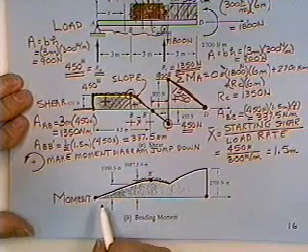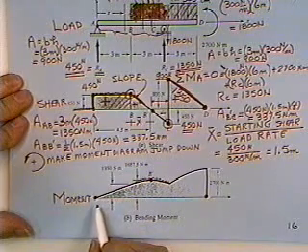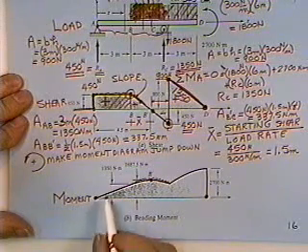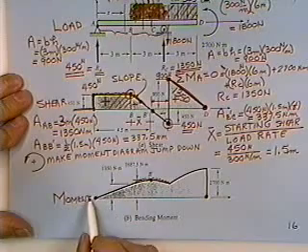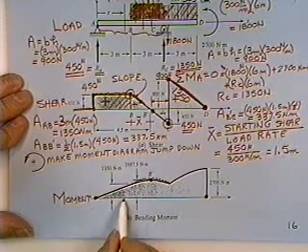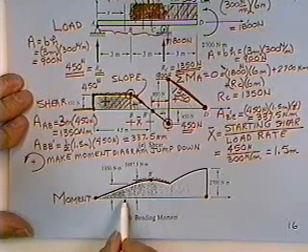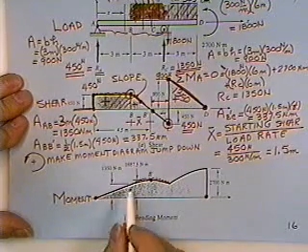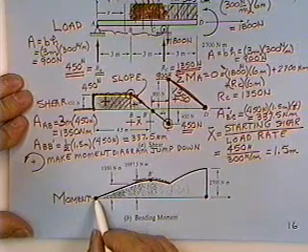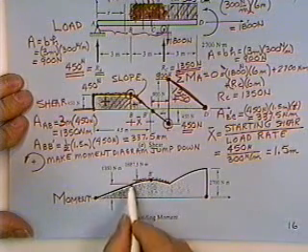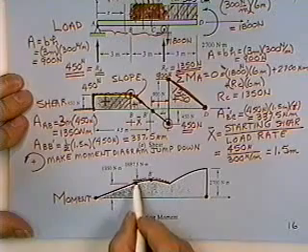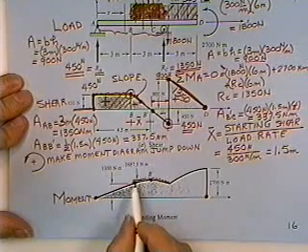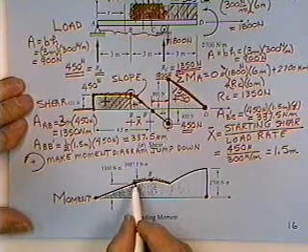All right, so now we're ready to draw the moment diagram because it is destined to close on 0. As always, we start on the left end of the beam and we work towards the right. That gives us the good sign conventions and keeps the little arrows so they tell us which way to go. The first area says, as you cover area AB under the shear diagram, I request that you end up 1,350 higher than you used to be.